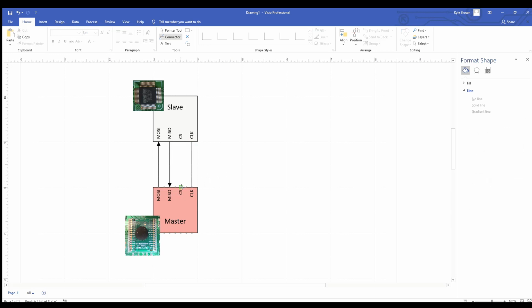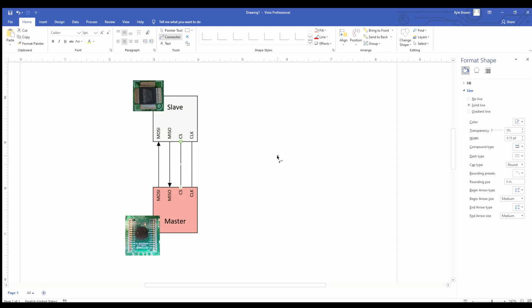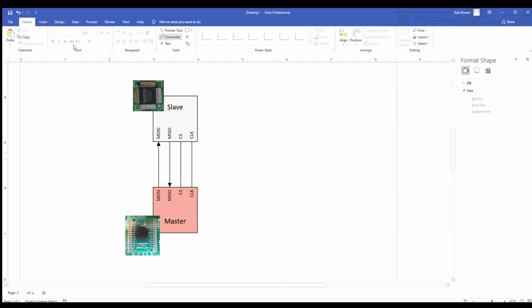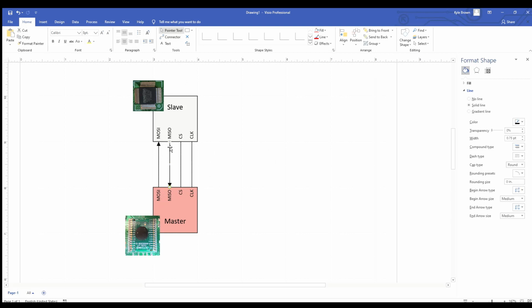If there are multiple slaves, the master can use the chip select pin to tell the slaves which slave it's talking to. In this machine, it looks like the slave doesn't do any talking. So we have the MOSI pin that the playfield uses to talk to the Backbox, but the Backbox doesn't say anything back. So there is no MISO pin. There's only one slave, but there's still a chip select. Sometimes, even when there aren't multiple slaves, the slave devices need the chip select to transition between high and low to begin their operations. We'll see if that's the case on this one.